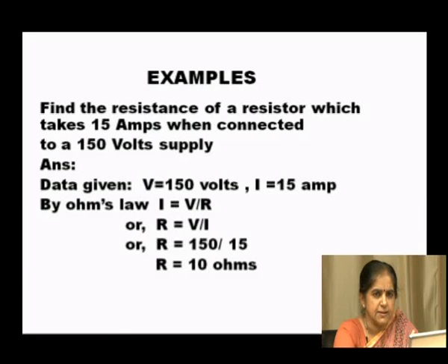So, with this information, let us try to solve some of the problems based on Ohm's law as well as series and parallel connection of resistances. So, let me summarize the characteristics of series connection. In series connection, the effective resistance will be equal to the algebraic sum of all the resistances, and same current passes through all the resistances, whereas in parallel connection the voltage applied is same, whereas the reciprocal of the effective resistance is equal to the sum of reciprocal of all the resistances in parallel connection.